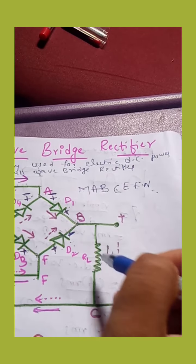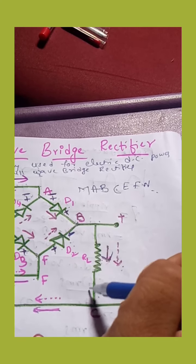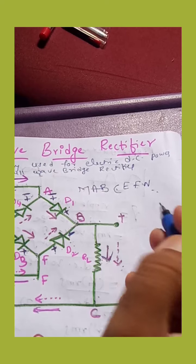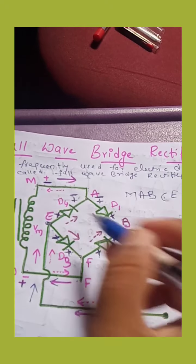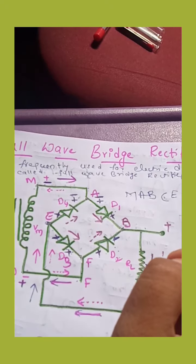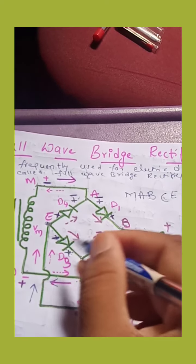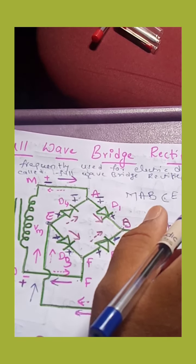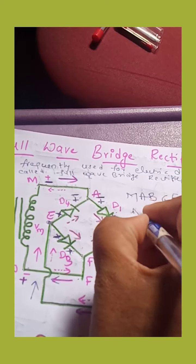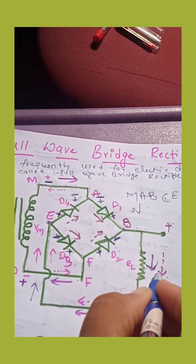At the load resistor, the current, this solid arrow you see, is from B to C. Now in the negative half cycle, D2 and D4 are forward biased. Here terminal N is positive. The current starts from N. You see the dotted line arrows.